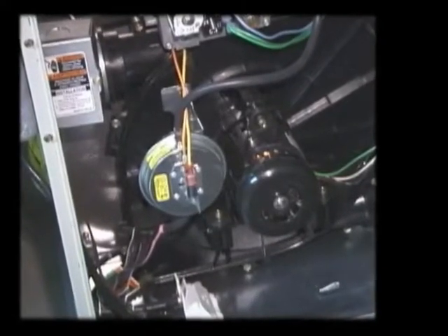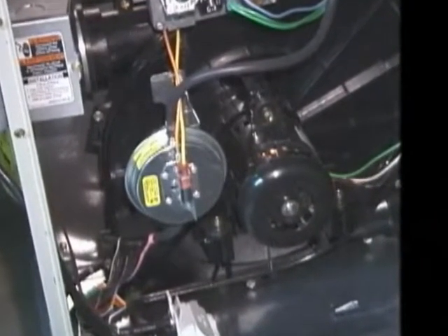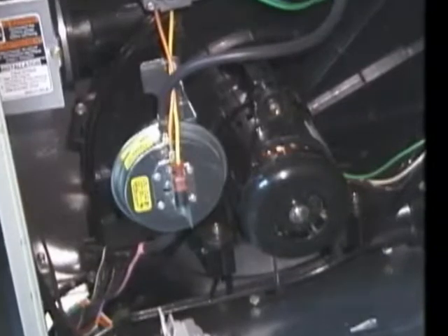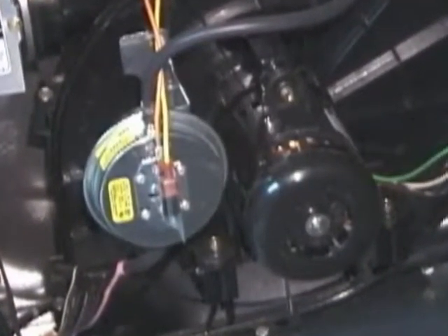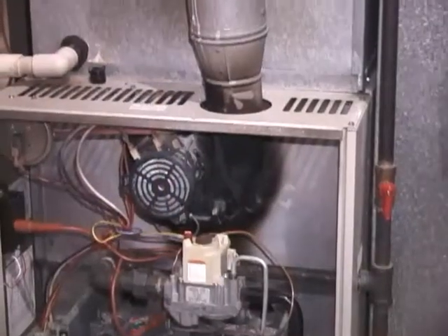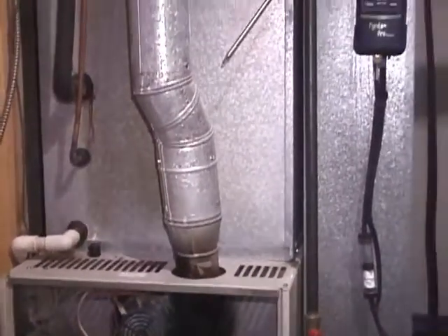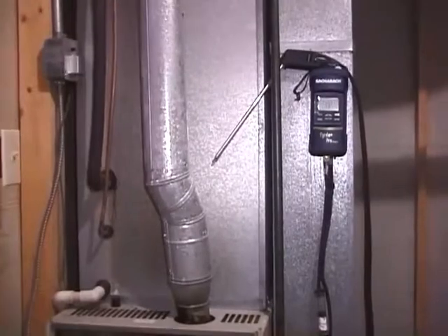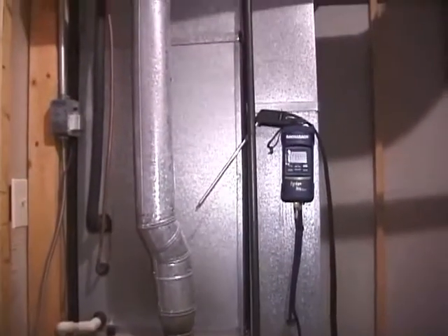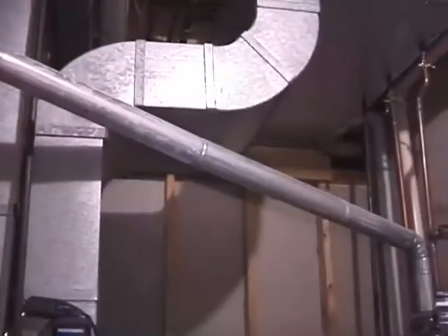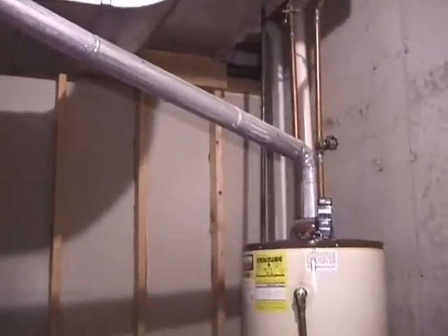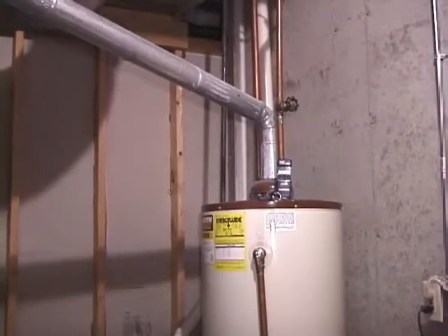These units also have a pressure sensor that will shut the system down if the correct negative pressure is not indicated at the inlet of the fan housing. However, in the previous example of a Category 1 fan assist type furnace that is common vented with a water heater, its pressure sensor won't operate because the system can vent out through the draft hood of the water heater. So the fan is still able to draw in combustion air at the normal pressure.